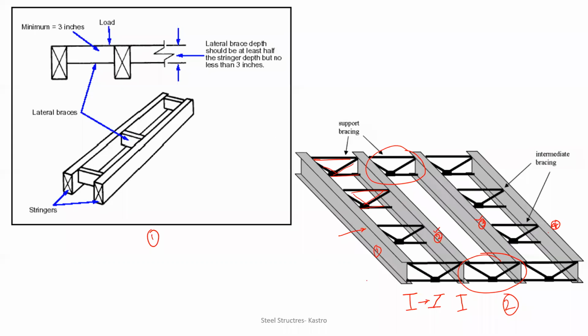It is because the first and fourth beams are laterally supported. They have proper supports. Even the second and third beams are also having supports, but they are having supports at the edges of the member. They don't have supports at the intermediate portions. So when they don't have supports at the intermediate portions, it is very clear that you might experience bending in the member, and this bending will also be accompanied by a certain kind of twisting. So this is what the laterally supported beams are.